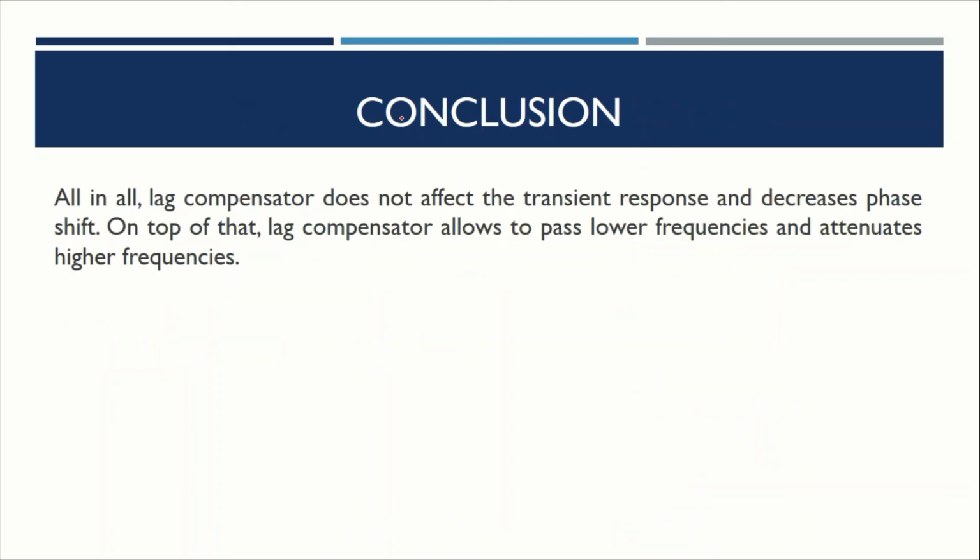Lastly, for the conclusion, all in all, the lag compensator does not affect the transient response and decreases phase shift. On top of that, the lag compensator allows lower frequencies to pass and attenuates higher frequencies. Thank you.